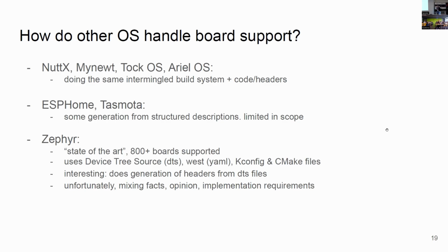And yes, then there's Zephyr. Zephyr is basically the state of the art in this. They have the most board support of them all. They are using device tree source files and YAML files, Kconfig, CMake files, but all the interesting stuff is in the DTS files, and they're generating board support from that, which is extremely interesting. And I think we should do something similar.